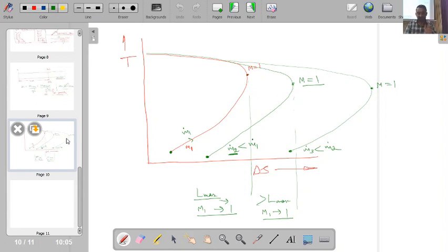So in case of subsonic flow, the inlet condition gets modified, whereas in case of supersonic flow situation, this condition will be adjusted by the presence of a shock wave within the duct. So the shock wave will modify the properties and create a discontinuity in the flow.